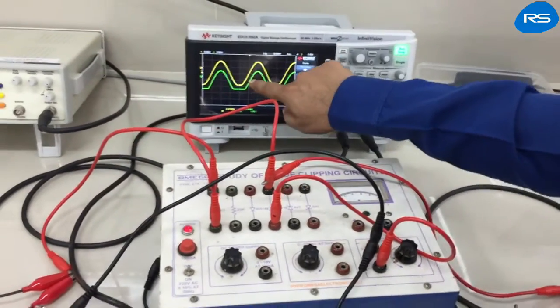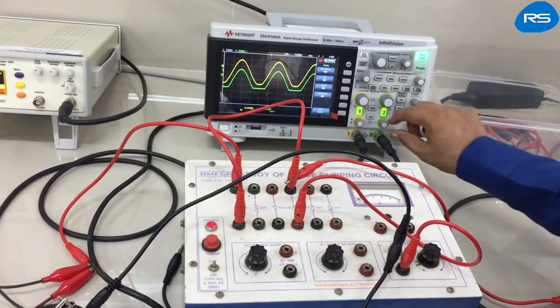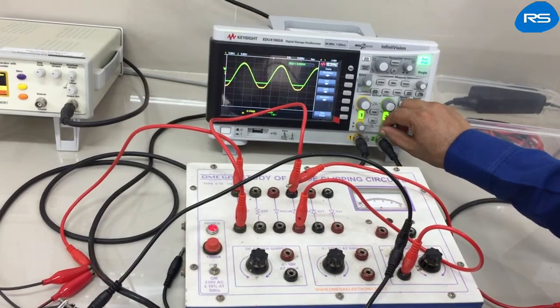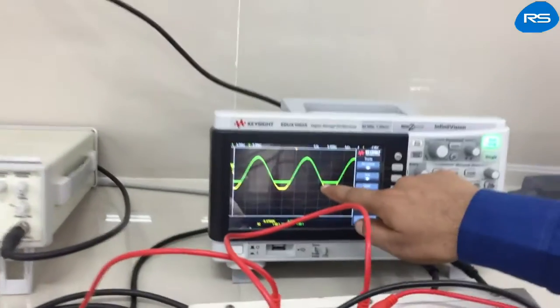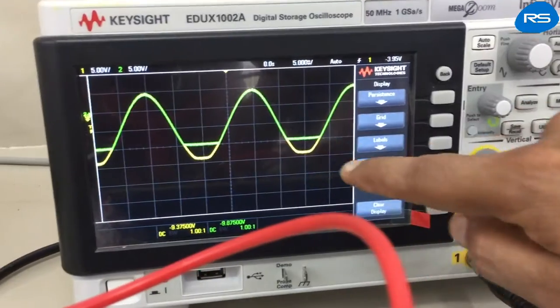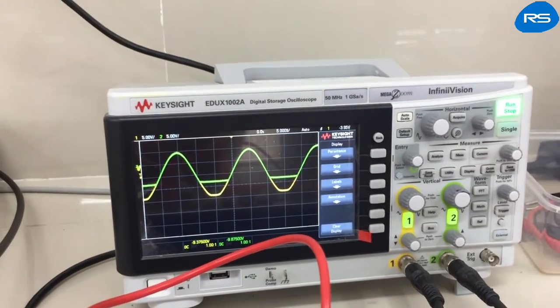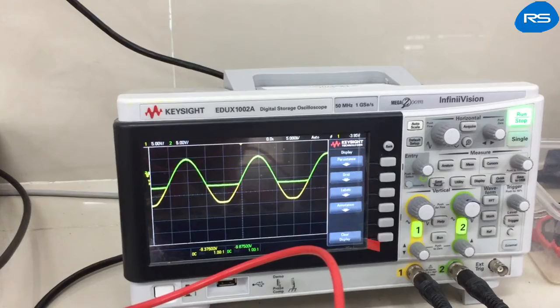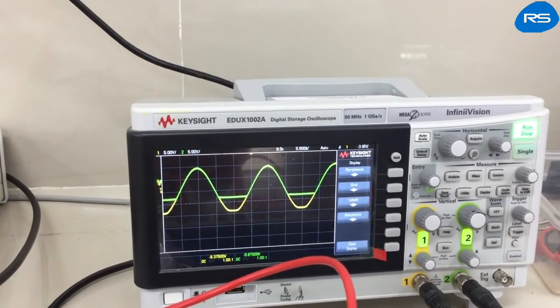Green signal is our output. You can compare the output by placing them on the same level. You can see that a portion of the negative half cycle is being clipped off, that is being controlled by this DC bias voltage. You can observe the variation in the DC bias voltage is shown in the output waveform.